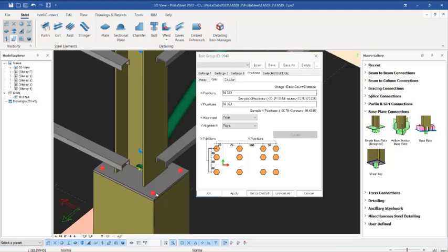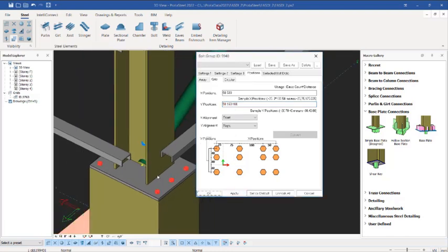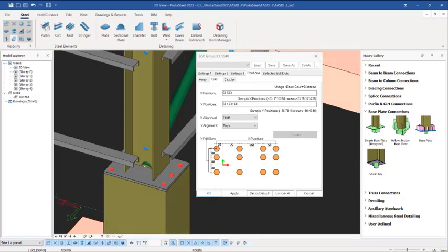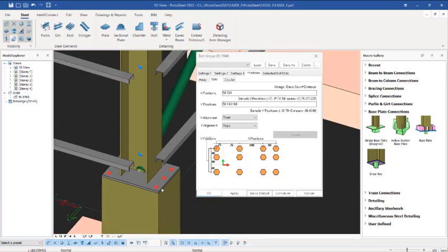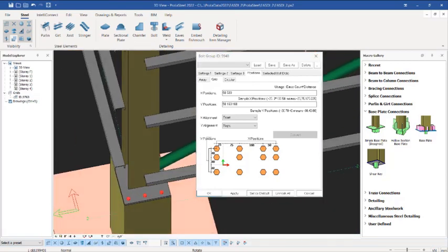If you want to have more bolts in this Y direction, you can divide this by 2. Let's say you can still have 150 or 160 right there. You give a space, you have another 160 right there. If you click on apply now, you see you're having 3 bolts right there. If you check this side, it's the same thing, 3. I believe this is fully understood.